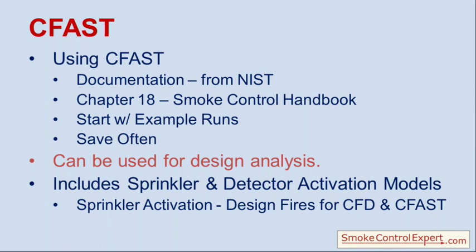CFAST can be used for design analysis of atrium smoke control systems. In the United States, that would be allowed in NFPA 92. I would not recommend doing that, but you can do it. I would go with other methods, the equation method or a CFD.